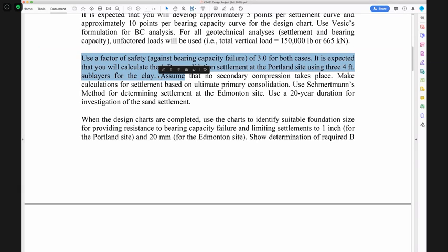And now that we're in as far as having stress distribution beneath loaded areas, you can gain appreciation that actually the delta sigma will change with depth. And subdividing that into little layers is actually beneficial because it allows you to assess that, hey, up top, you're going to have more settlement occurring, a greater delta sigma, in the middle, less, and down at the deep depths, even less.